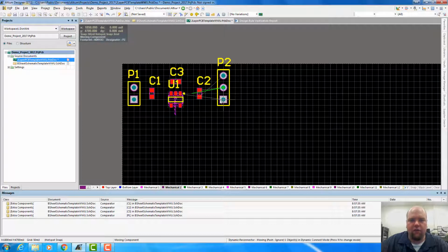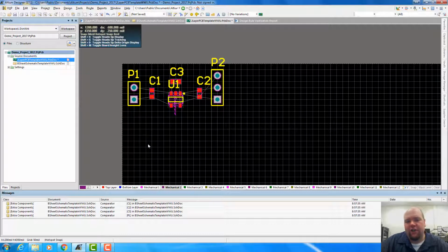So we'll move this guy over 50 mils to make sure these guys are all completely on a 0.1 inch grid. We could have just set our grid to 0.1 inch spacing as well, and that way we're guaranteed to have these things moved on a 0.1 inch grid. Okay, so this is a good general location. The next thing we're going to do is start routing these guys.